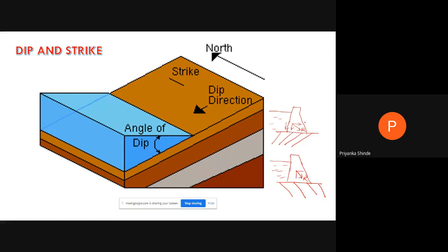If it is perpendicular, this will help to keep the dam in position, and even if there is some leakage along the bedding plane, this water is recirculated in the reservoir. But in the other case, if there is any leakage, the water will go downstream, and the purpose of constructing the dam itself will fail.